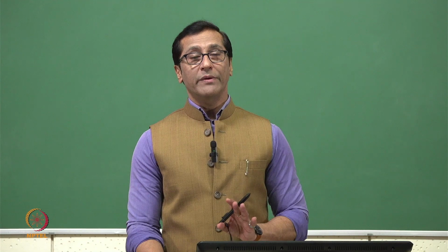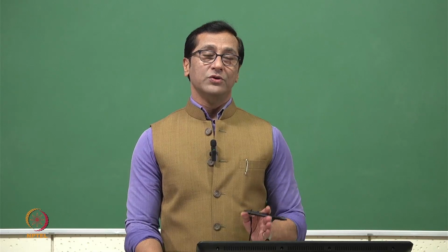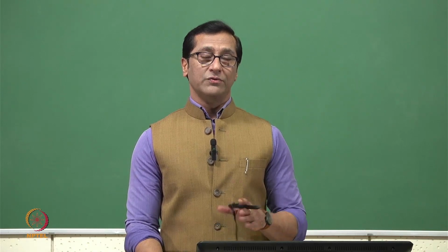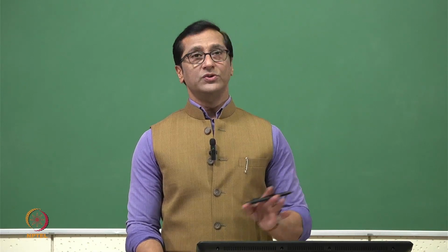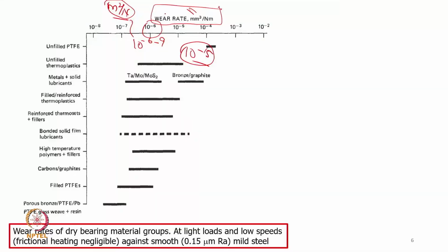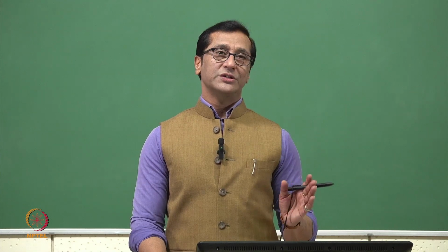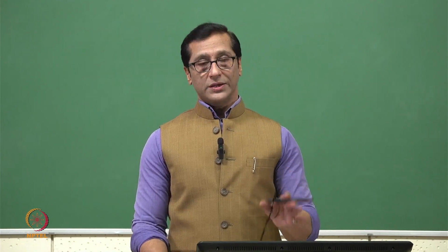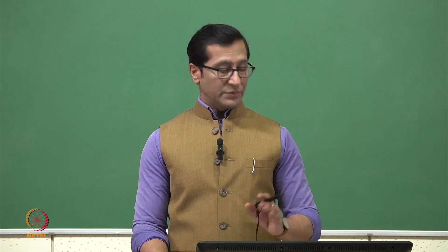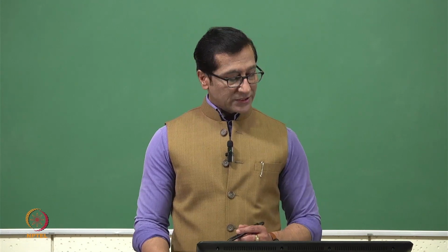The dimensions should match, and whichever we are tracking, the coefficient of friction, coefficient of wear or wear rate, that should be accounted for. And in an earlier slide I mentioned very clearly, this is a specific wear rate where the hardness has also been accounted. We don't separately account for the hardness. Here hardness is already built in.